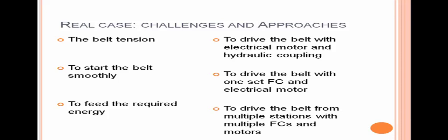But the challenge of setting the belt conveyor speed and controlling the amount of bulk material carried by the belt conveyor remains unanswered, because hydraulic couplings do not give us any ability to control the belt conveyor speed.